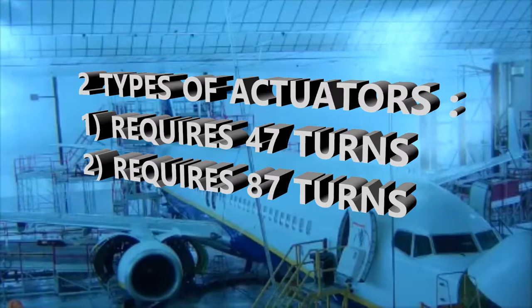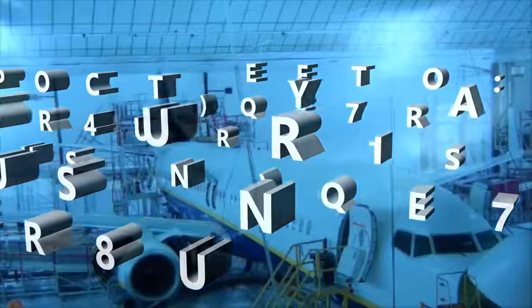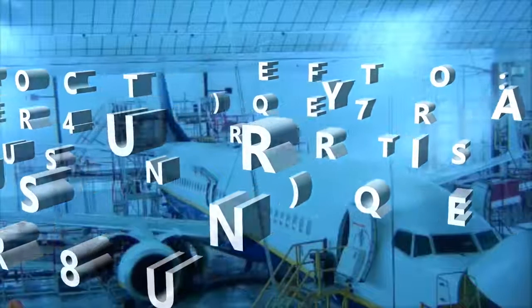You've got two. One requires 47 turns on the manual drive, and you have another one that requires 87. So how are you to know that? The fact is that actuators can look very similar to each other, but there are two different types of actuators there.